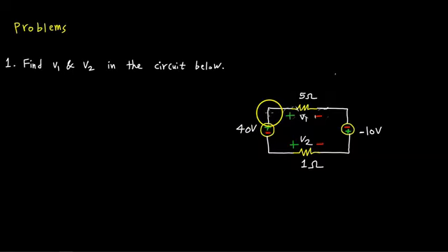Okay, so let's go ahead and find those voltages then. If we apply KVL, Kirchhoff's voltage law, I'll start here below the supply. I'll go in this direction, and that'll be my loop. Just call that I. So what did we learn? If I start from this node and I go up, I encounter the 40 volts, but I'm going to see the negative side first. So the first equation, the relationship that I have, is a negative 40 volts.